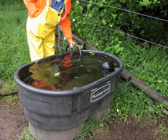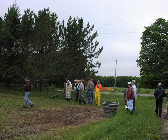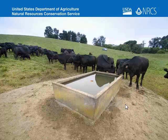So here's a portable tank that's been put up with the end against the fence, versus this where the flat side of the tank is against the fence, so there's less headspace for livestock to drink from it. And it's just important that we make sure we've got the amount of headspace we need for the number of livestock that are drinking from it. Here's an in-place tank. Bill showed one of these also.